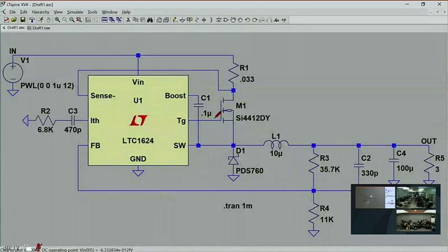It would be clearer if they labeled those pins for what they are. The output of the gate driver goes to the gate. The ground connection of the gate driver is the pin called switch. I mean, you don't really want a pin called switch. You want to buy an IC, apply power, connect the gate to it, and have it switch and drive the gate. That's all you're really interested in.